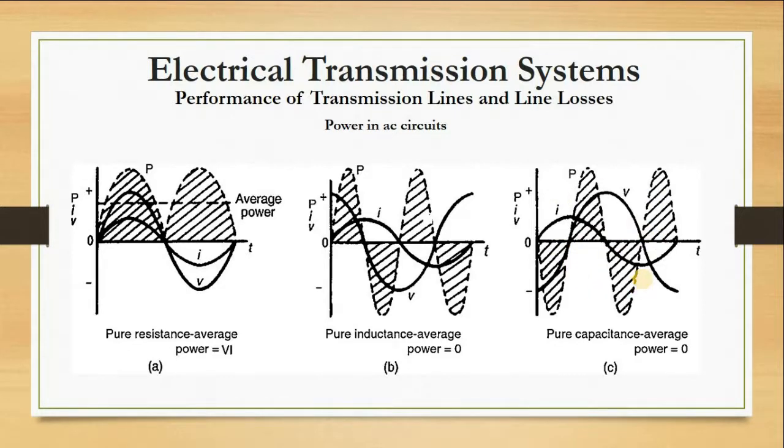This is very simple. When we talk about a lagging power factor, we know power factor is the cosine of the phase angle between the voltage and current. Now when we say power factor leading or lagging, usually in power systems, the reference is made to the current. They will not tell you the power factor while the voltage is lagging. Once they say a power factor of, let's say, 0.7 leading or 0.7 lagging, they are making reference to the current. So you should take note of that.